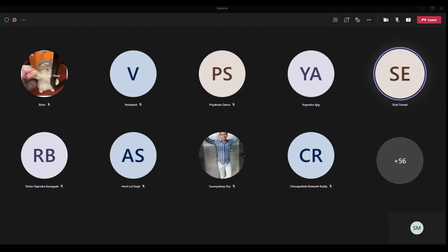Can you describe the function of VSS1? I think you mean VCC1, right? I tried to search for it, but somebody said it was written as VSS, so I got confused. It might be some other kind of nomenclature, but usually it's VCC1, and the L293D needs a high 5 volts at VCC1 to function properly. Whatever functionality you are seeing, you need 5 volts at VCC1 and a 0 at ground.